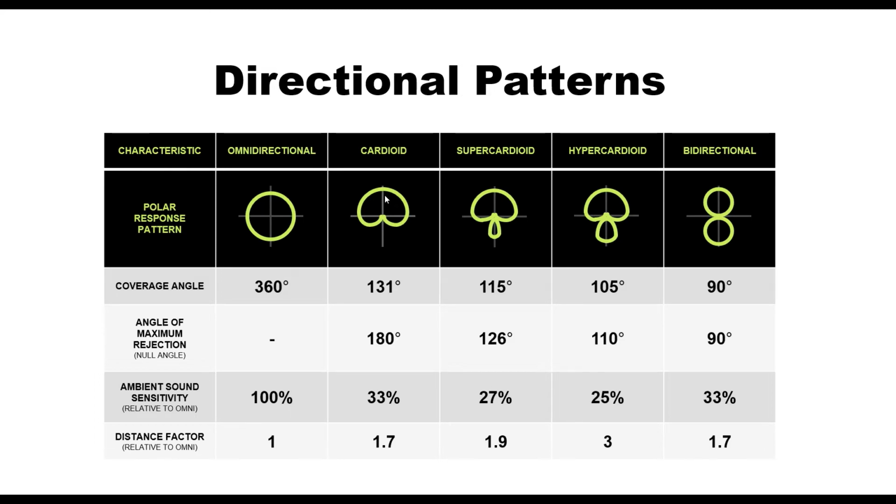The reason those microphones can still be omnidirectional, yet you don't have feedback issues with them, is because that microphone is millimeters from your mouth. And because it's so close to your mouth, you can turn it up and even walk in front of the loudspeaker often because you're not asking for that much gain because it's so close to your mouth.